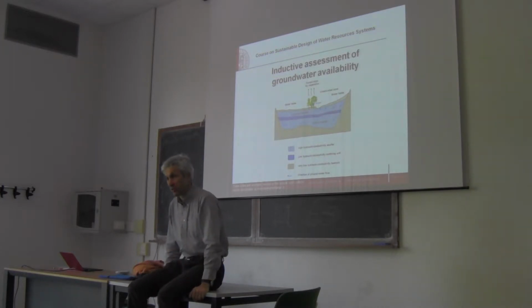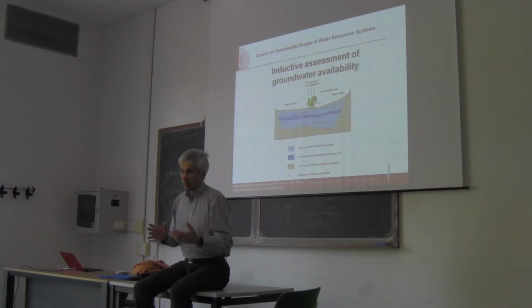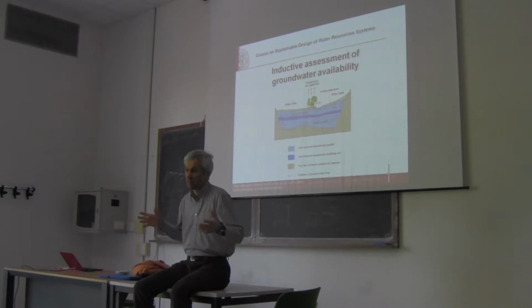So what is the purpose of observing groundwater level? The purpose is very clear. We found a groundwater resource, we start taking water, and after taking water, we want to monitor if the groundwater level remains undisturbed, not impacted by the withdrawal, or gets lower. If it gets lower, it means that we are depleting. We are taking more water than what is given by recharge, groundwater recharge. This is the technical term.